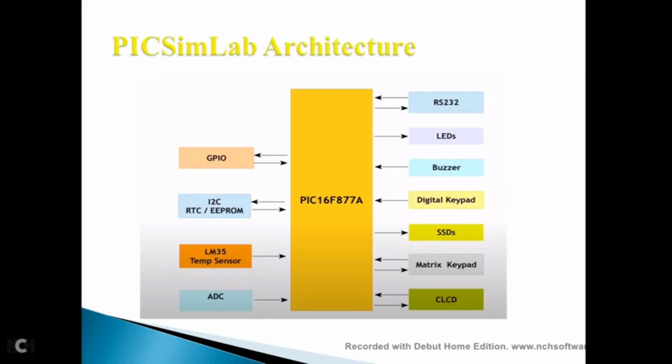This is the architecture of PICSimLab. Here we can see the PIC16F877A microcontroller, which connects to several modules, such as GPIO modules, RTC and EEPROM, LM35 temperature sensor, ADC, RS232, LEDs, buzzer, digital keypad, SSDs, matrix keypad, and also CLCD. The arrow indicates the data transfer path.